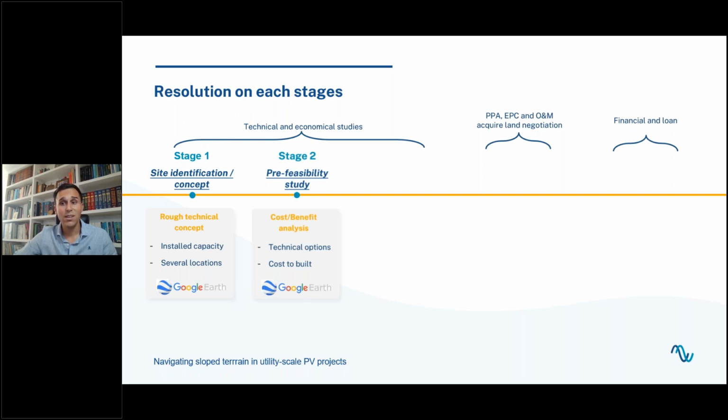But as we previously mentioned, if you have significant slopes exceeding 8, maybe 9% north-south, even east-west, it's recommended to compare them between default and custom in order to see what's the technical difference, for example, in the bill of quantities, the number of structures, the number of inverters, even the distances to the fences and so on.